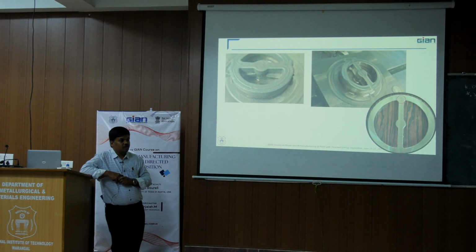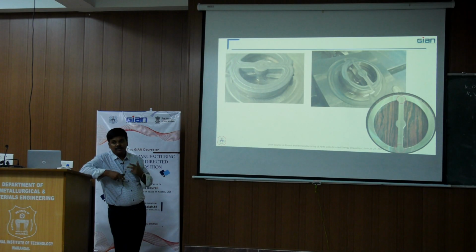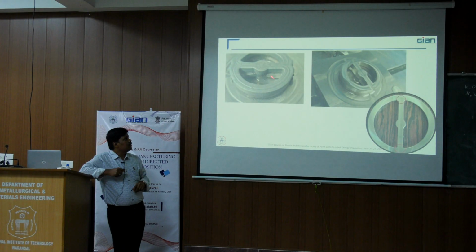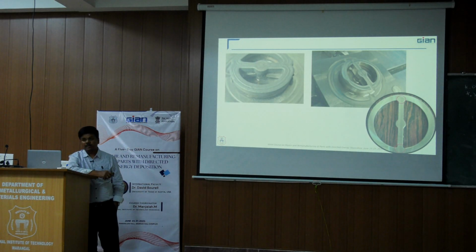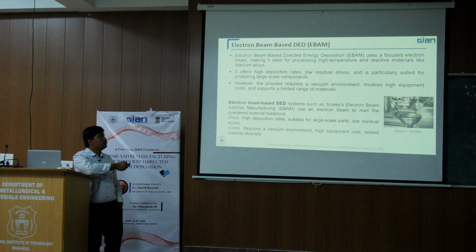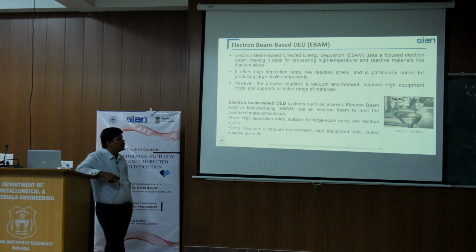To address these issues we made several iterations to bring it back to normal, to effectively use our laser DED process for the applications. Different types of strategies we adopted instead of going for this linear strategy. We adopted different kinds of scan strategies that are able to minimize these kinds of defects in the downstream components. The another one, as I told, electronic manufacturing process.